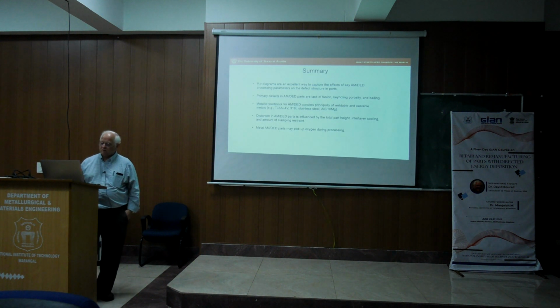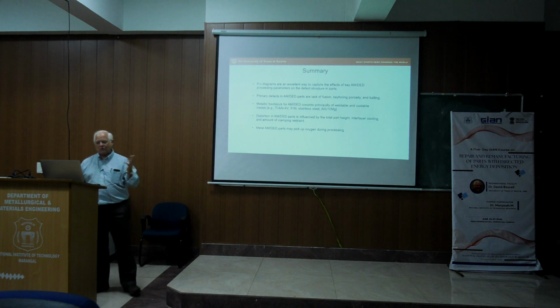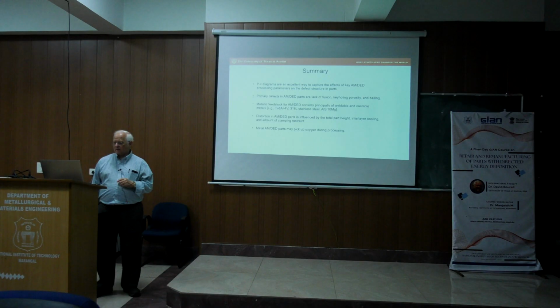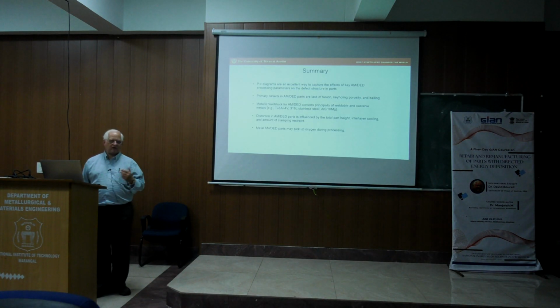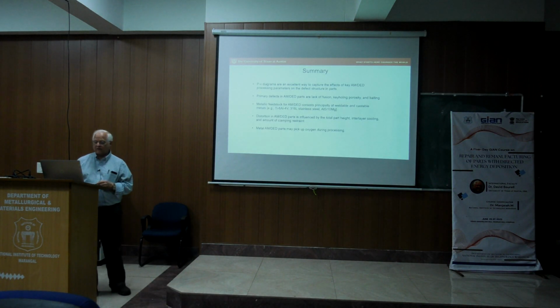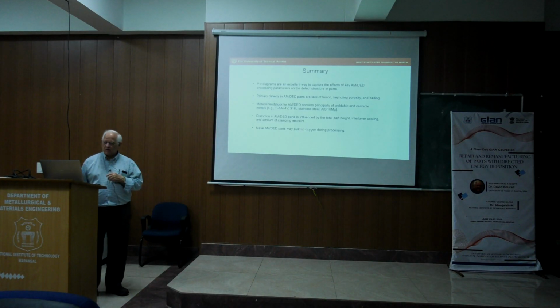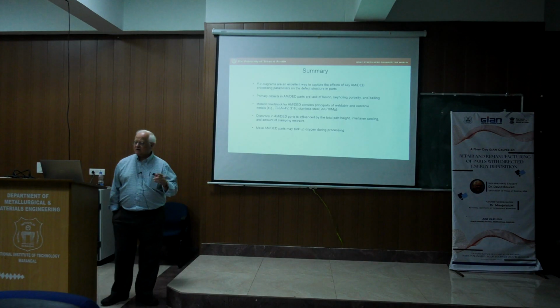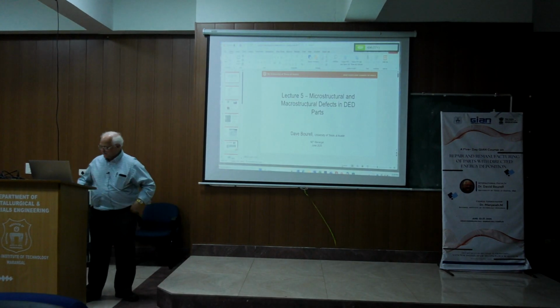Distortion is influenced by the total part height, air cooling, and the amount of damping and restraint. That's what we see on these. So we can do some things to try to control distortion, but it still is a very real factor. And then, of course, metal parts can pick up contamination in processing, virtually everything except titanium.